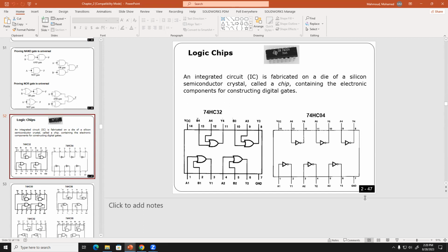Most of the time, the hardware is the normal way, but you can do the other way. That's why I want you to read the data sheet. For most of the chips, usually it's a low voltage, 0 volt and 5 volt. It's something we discussed: 0 volt for logic 0, 5 volt for logic 1.